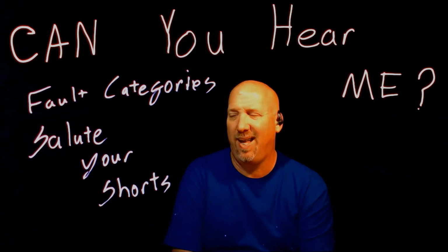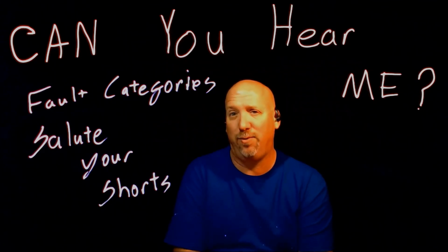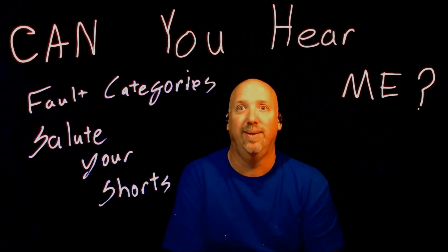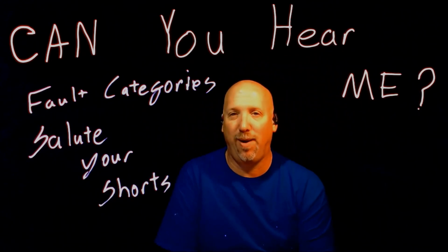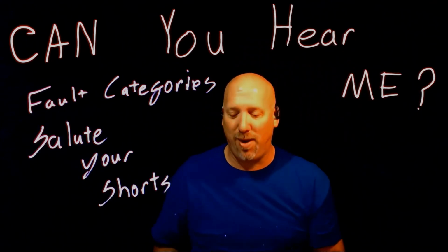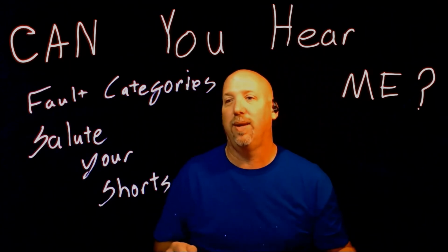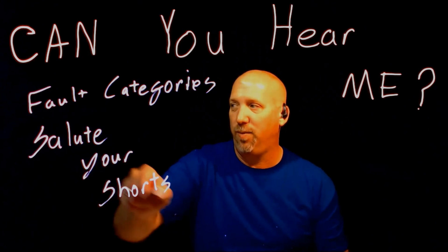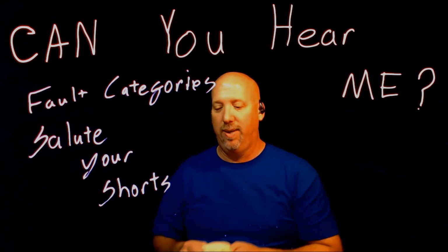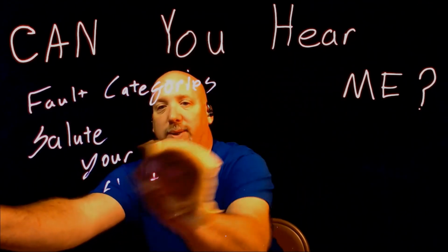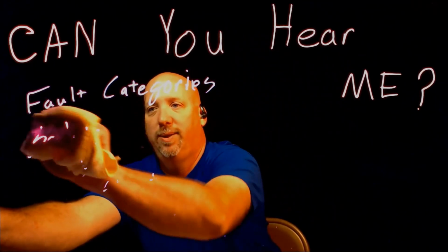And a lot of times in these CAN networks, you'd rather have a module fault than a wiring fault. If you've had to pull apart wiring harnesses, I'd much rather have a module fault than a wiring fault. So salute your shorts. If you've got a shorted wire, that's what you have to think about. Now if we're talking about opens, oh my goodness. Let's talk about opens now real quick.